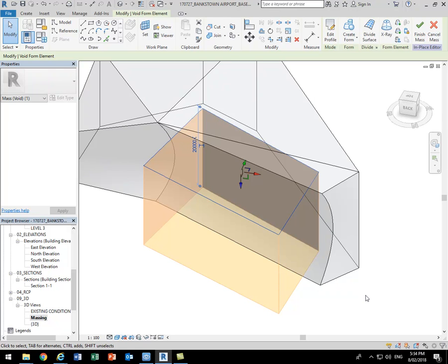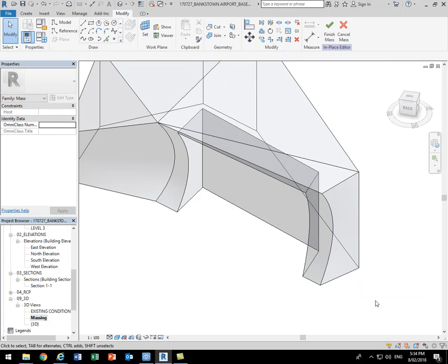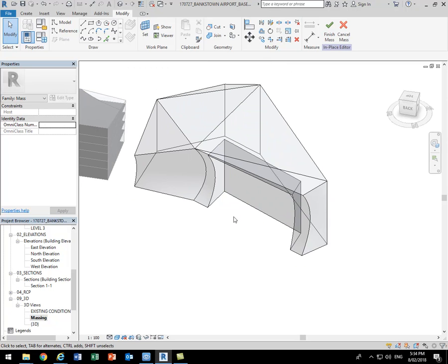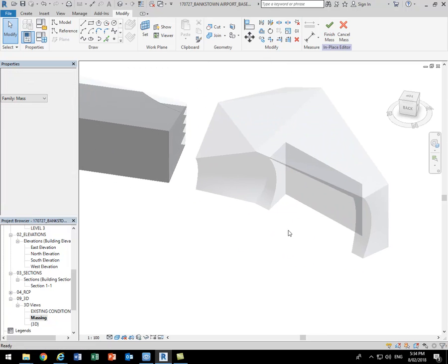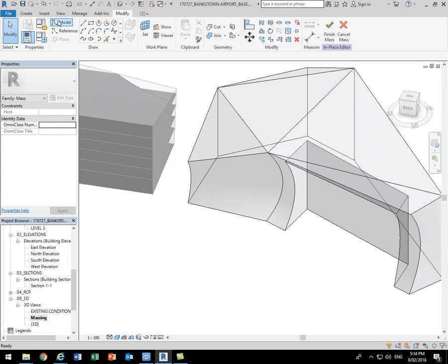Now, if I click to one side, I'm fairly certain that it will subtract automatically. And if you've seen it not do that, if you've seen it stay orange, it's because the void isn't overlapping the other element. So in this case I made it, it does overlap and it's cut away automatically. I'll just go and make another one.